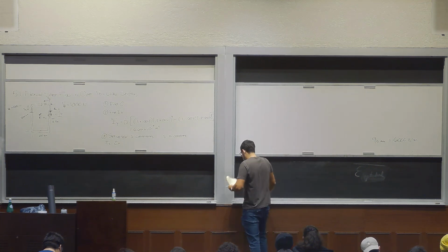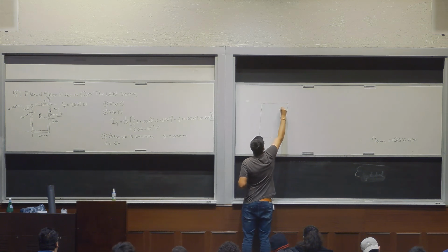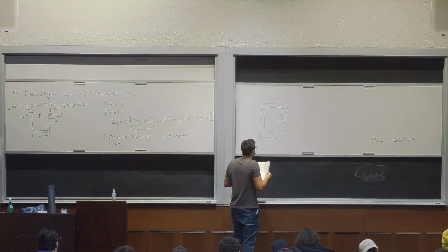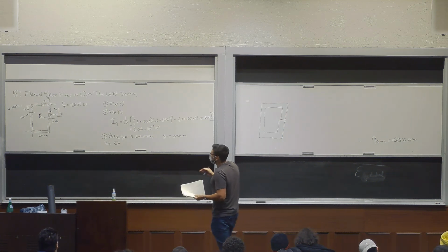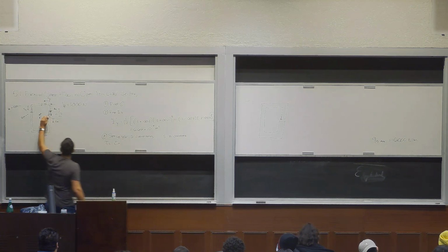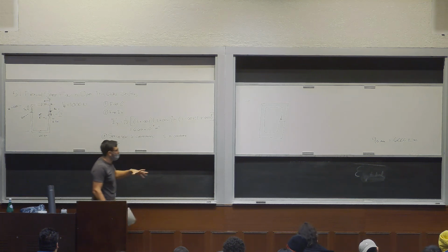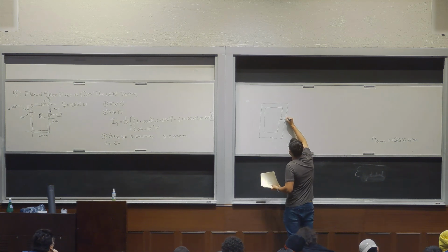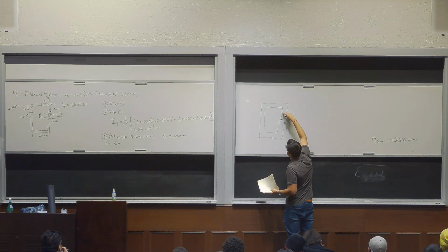All right. So we have this cross section. It's not perfect, but whatever. I forgot to stress this, but hopefully it made sense. At the cut section, the location of the cut, this shear flow is always going to be 0. So you always start with 0, and it increases. Why does it start with 0? It starts with 0 because there's basically no area. Q increases with area and the Z position of the centroid, so it starts increasing, and at the beginning it's always 0.